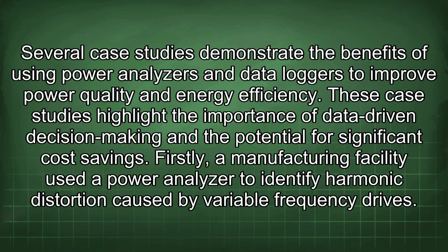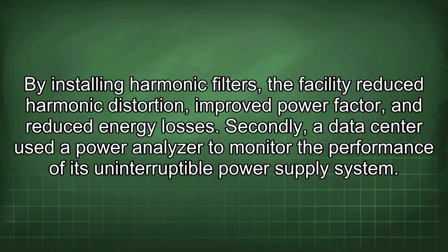Firstly, a manufacturing facility used a power analyzer to identify harmonic distortion caused by variable frequency drives. By installing harmonic filters, the facility reduced harmonic distortion, improved power factor, and reduced energy losses.